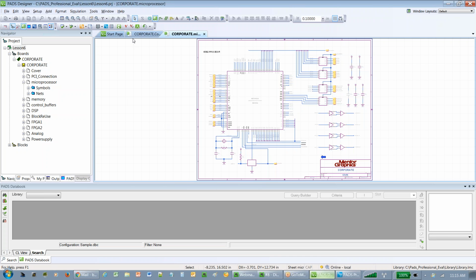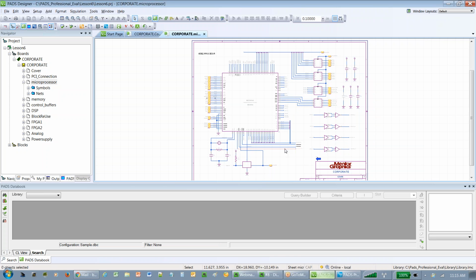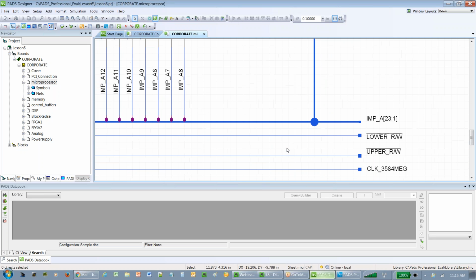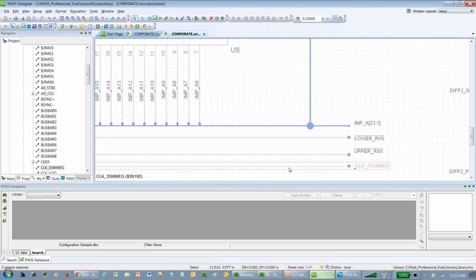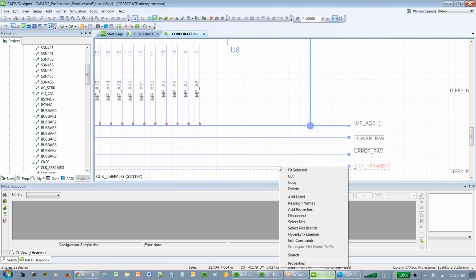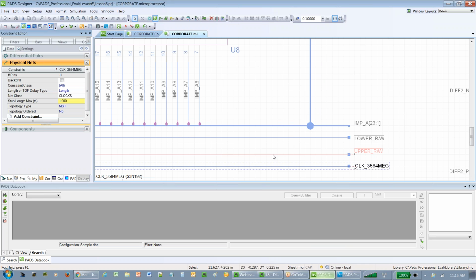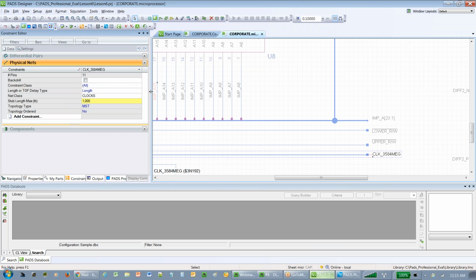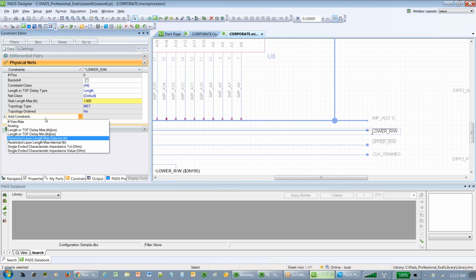Okay, so if I go ahead and launch the Constraint Editor system from in here, this one has the advantage that I was trying to show in the PADS one, where if I click on this net and I want to see that net in the Constraint Editor, I can just right-click and choose Edit Constraints from the right-click menu, and it opens up a built-in window for actually looking at your constraints. So no longer do I even have to bother going to the manager tool. I can just click on a net and see those constraints right here in this window. I can adjust the constraints. I can change items on the fly to do my design rule process.